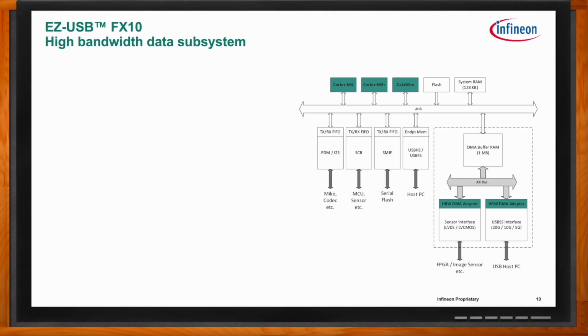Sure. FX10 is an interface controller, which means you've got data from one side sending to the USB side. It's actually quite challenging when speed goes higher to interface to your data sink or source for your application. The old FX3 supported a 32-bit LVCMOS interface, which is not enough when speed goes higher. So we tried to design this interface as flexible as possible so that any application can leverage the FX10 for their higher bandwidth needs.